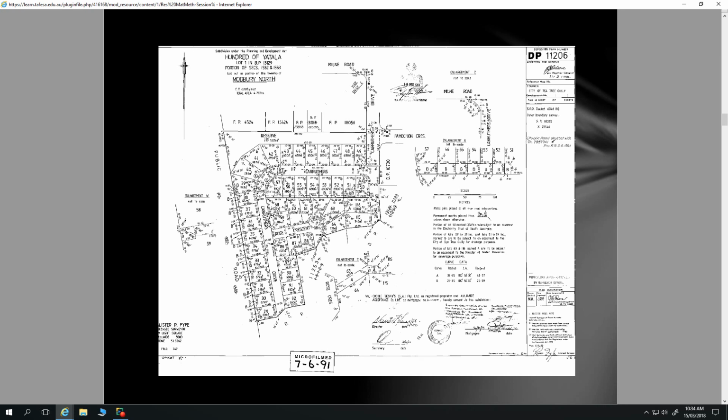So we have this long easement along the back of those ones there, which indicates the likelihood of these being on the low side of the road, and also of 115 and 116 being on the low side of the road. They would want to be draining their stormwater through to here. 115 doesn't actually have any development happening at this stage, so it doesn't require a drainage easement. You can drain stormwater out that way, but number 116 certainly does. So that's possible.